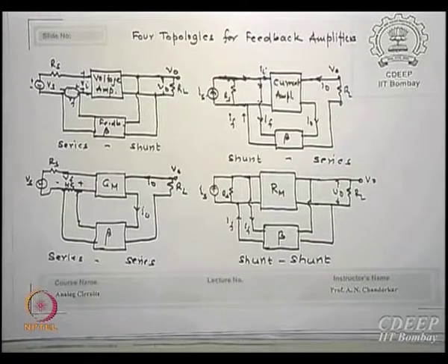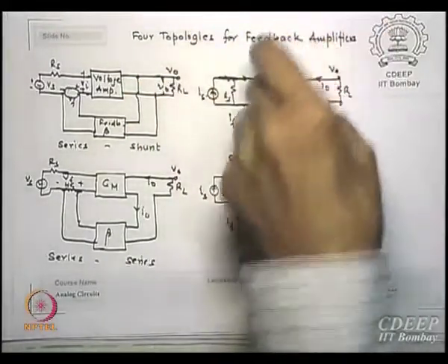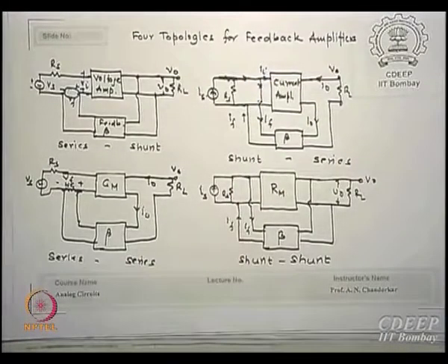Why does it stabilize? If that current increases, then the feedback will reduce it, negative feedback. If it reduces, the feedback is lower and therefore input rises, so output rises. So it settles itself to a value, with shunt inputs, shunt currents here, and currents picked up in series from the output. Such amplifiers are called shunt series amplifiers.